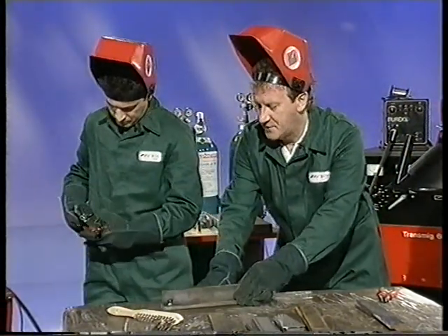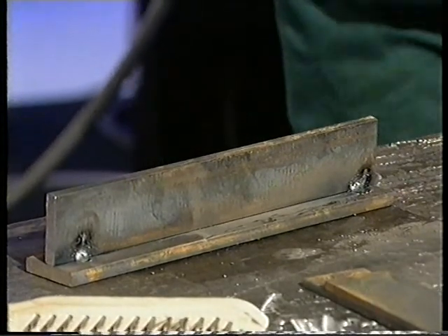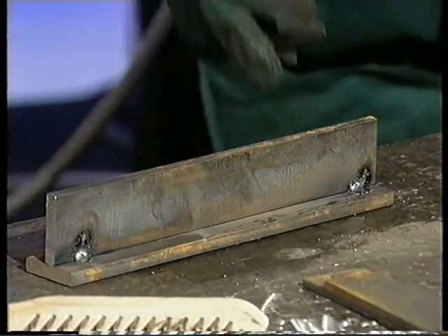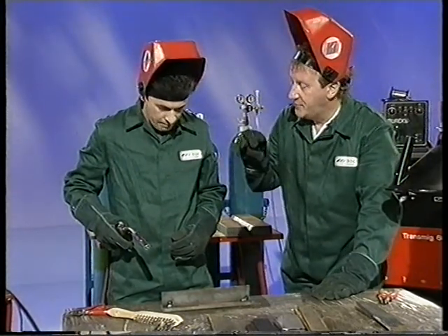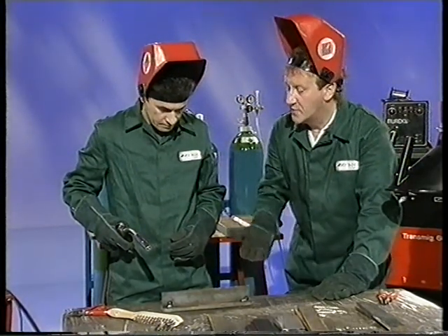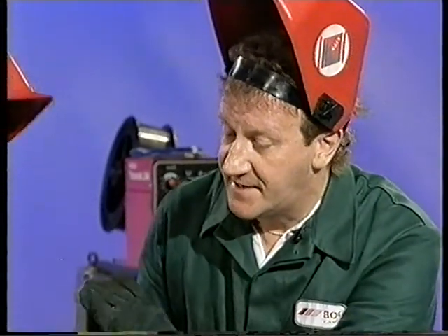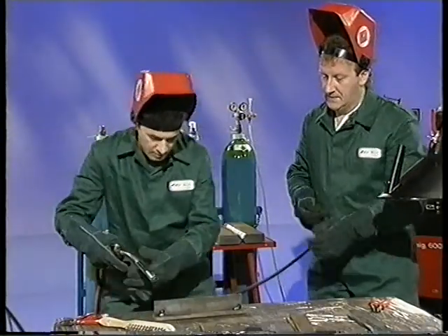The condition itself can vary on the amount of stick out that you allow. As you have greater stick out, on that particular wire feed setting, the current will drop. If you go closer to it, the current will increase. So it's dependent on the stick out that you hold. I may need to slightly adjust the machine to get an optimum condition. But it is obviously a good idea to keep a steady hand as you go.